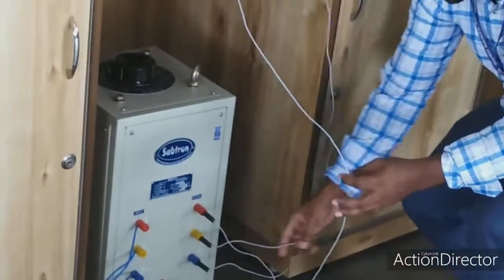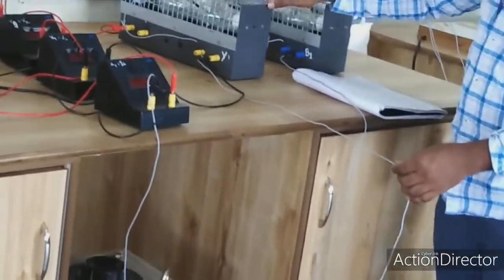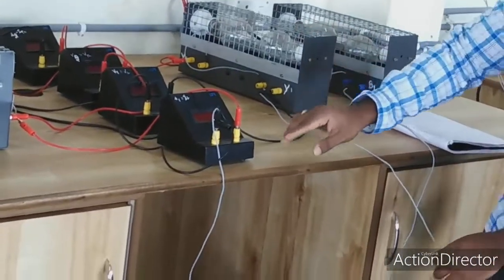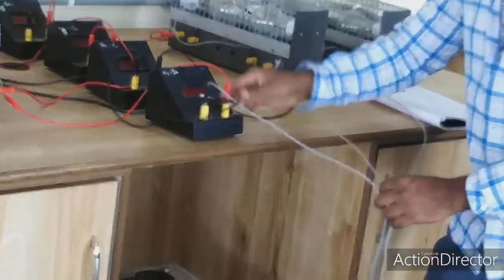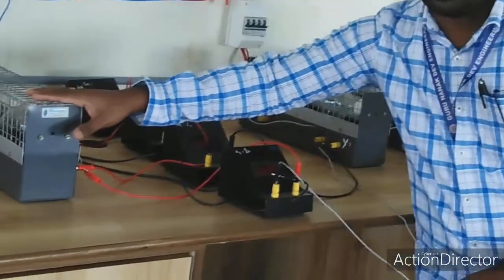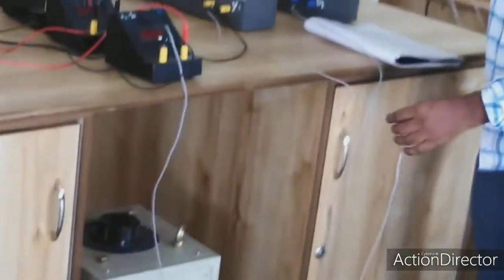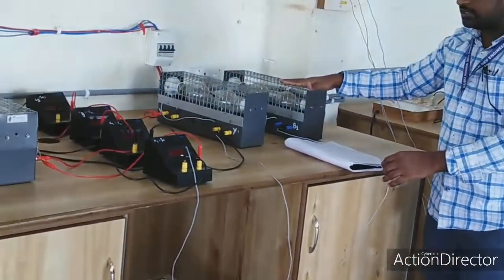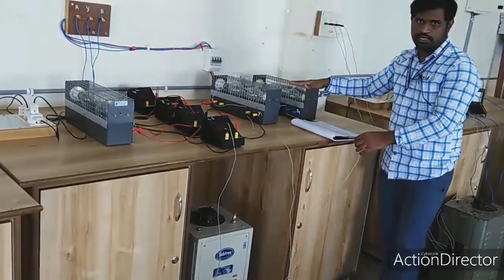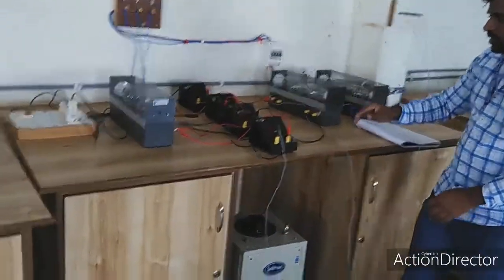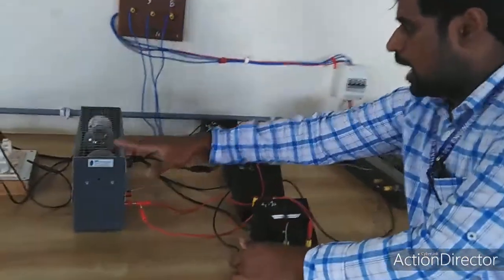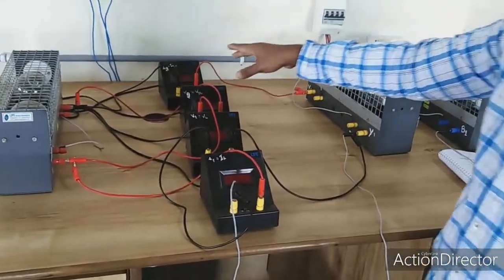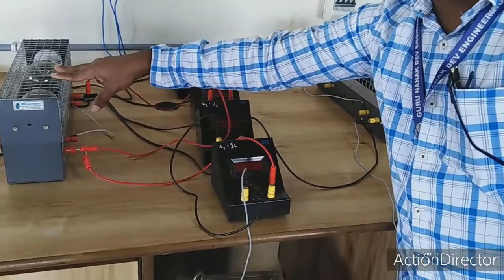Similarly, I am going to give the second line to the second load. So from the first I have given to the ammeter, and this ammeter is given to the first load, and the second is given to the second load, and the third wire is given to the third load. Like that, for the three resistive loads I am giving the starting connections. Later on, this ammeter is connected to the first load, and the ending point, it is a star connected load. So for all the star connected loads, the end points should be connected.